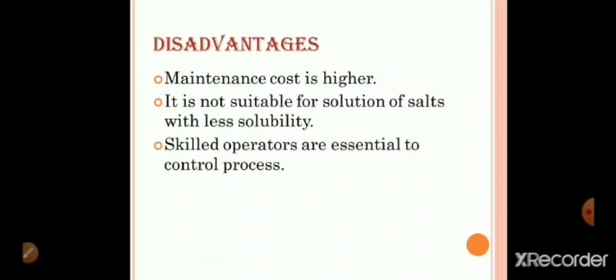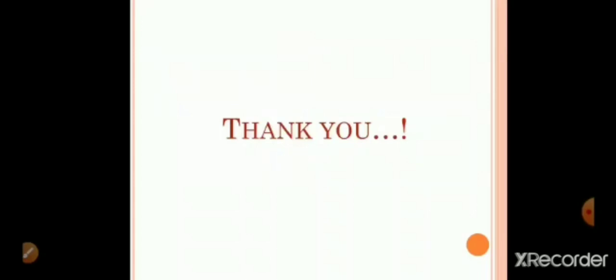Disadvantages of the drum dryer. Maintenance cost is higher. It is not suitable for solutions of salt with less solubility. Skilled operators are essential to control processes such as controlling the feed rate, film thickness, speed of rotation and temperature. Thank you.